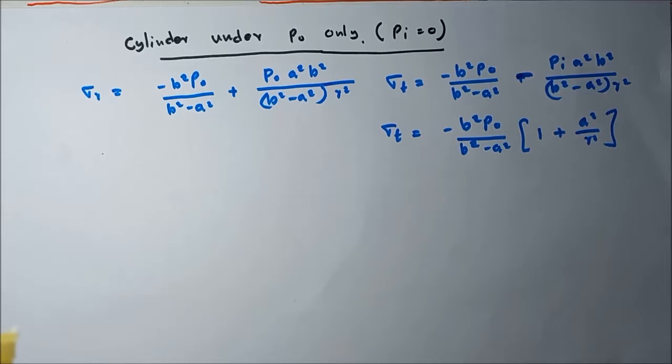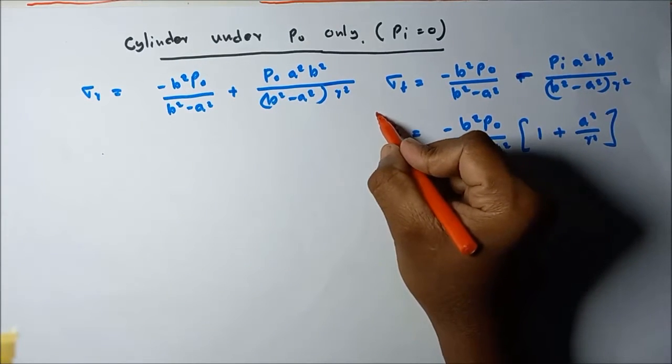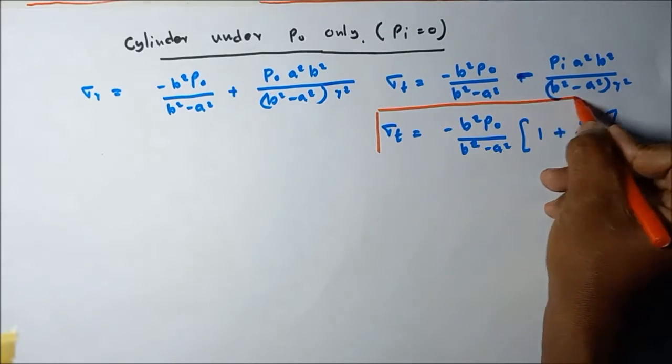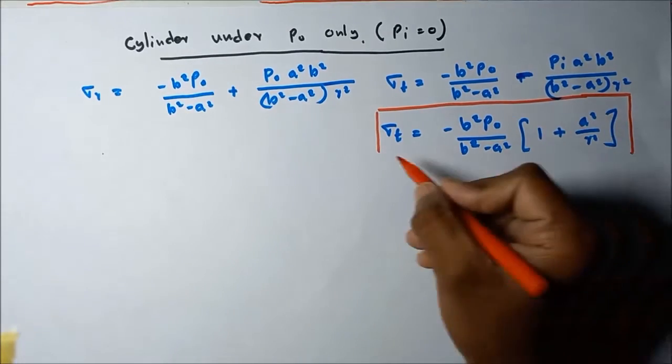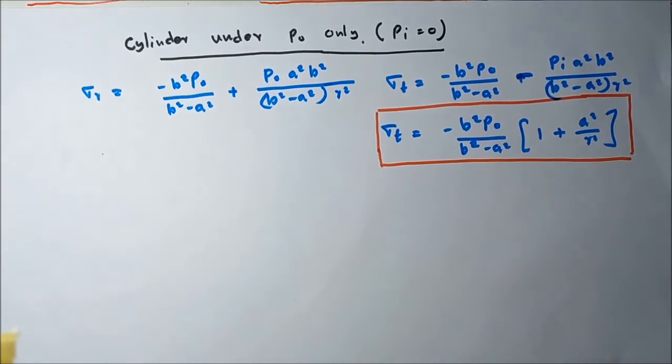This is the equation we can use to calculate the tangential stress when the cylinder is subjected to external pressure only situation.